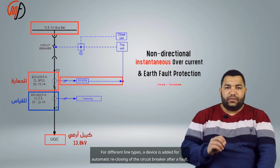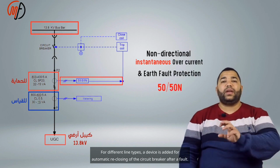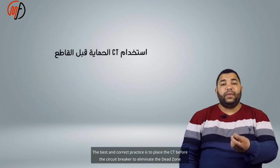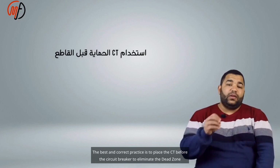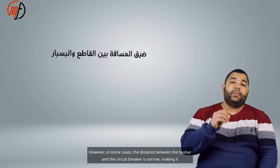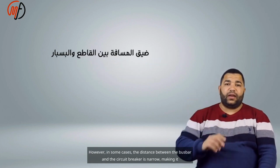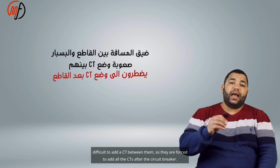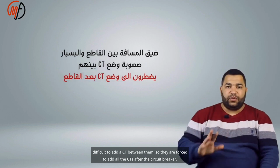For different line types, a device is added for automatic reclosing of the circuit breaker after a fault. The best and correct practice is to place the CT before the circuit breaker to eliminate the dead zone between the CT and the circuit breaker. However, in some cases, the distance between the bus bar and the circuit breaker is narrow, making it difficult to add a CT between them, so they are forced to add all the CTs after the circuit breaker.